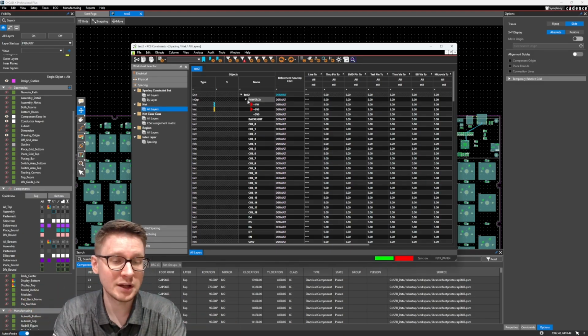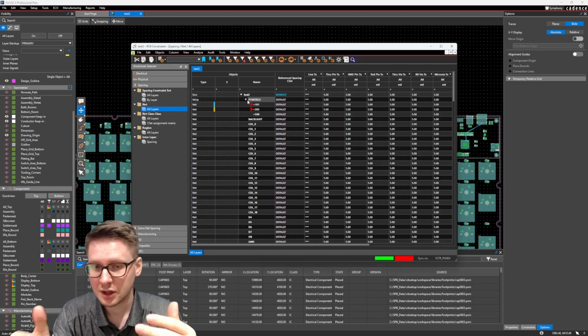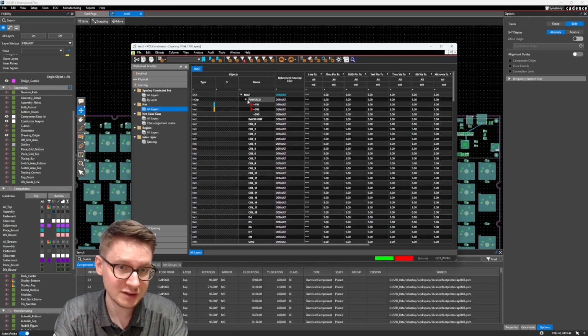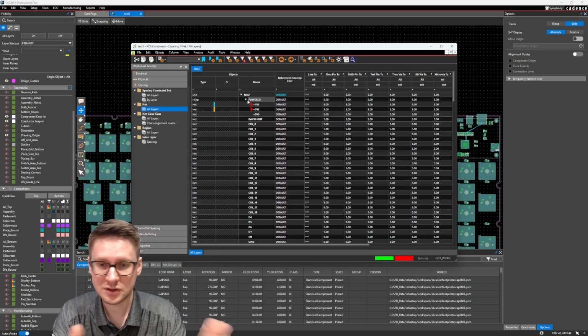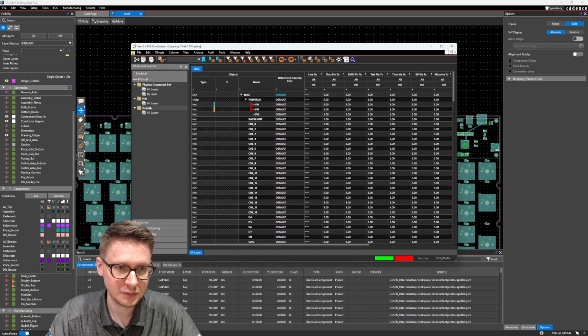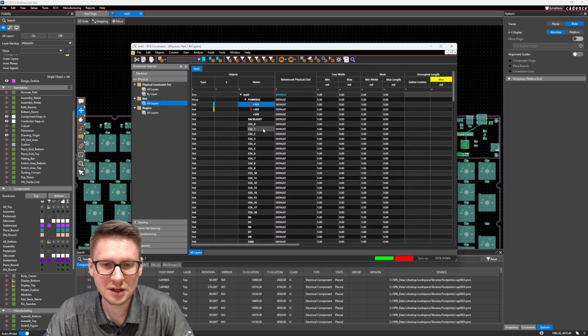And we're going to use that to our advantage because we want to assign specific rules to all of our power nets and then different rules to, for example, all of our signal nets, and make sure that we can set different rules without having to redo our work. Okay, let's go back to the physical section.